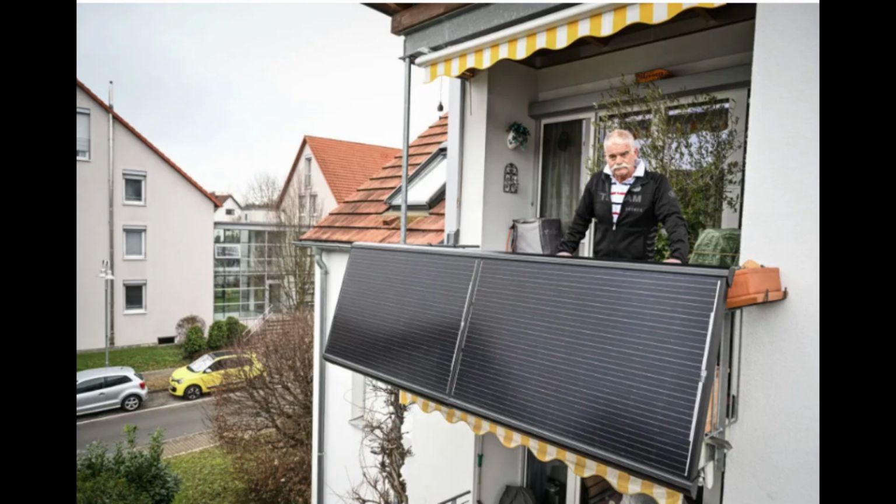Now there are also bifacial panels that can absorb power from both sides of a panel. It is practical to use a vertically mounted solar panel with a front side facing east to catch the rising morning sun and the back side facing west to catch the setting afternoon sun. Solar panels are now cheap enough for roofing or privacy fencing. But combining power from these different panels with differing illuminations is a real challenge because they all have different MPPs.